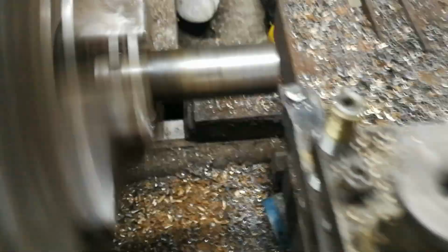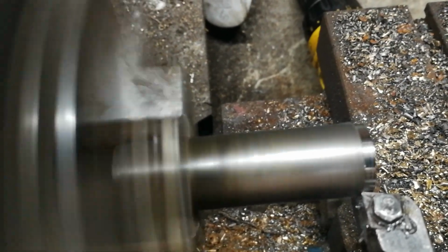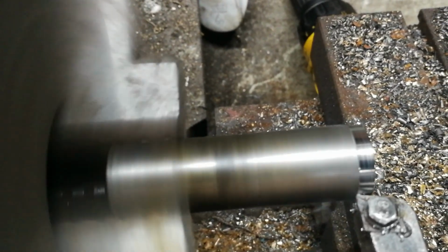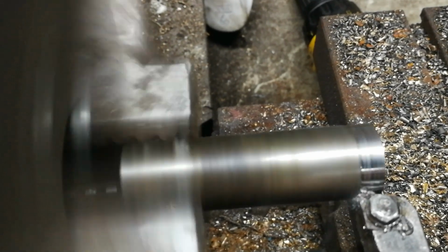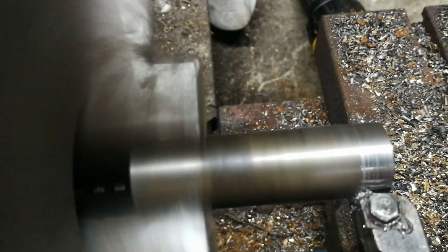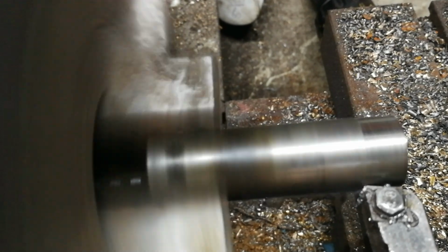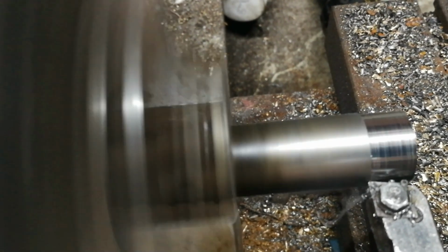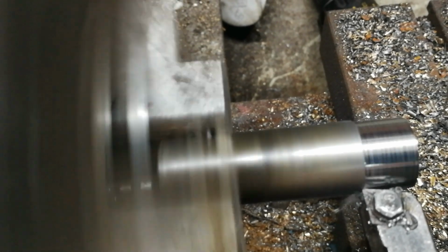You should avoid using coolant when turning cast iron or brass, as the fine filings from these materials will build up in the sump or T-slots of the machine. For machining cast iron, it is recommended a face mask should be worn due to the graphite dust that is given off. Coolant, where used appropriately, can extend the life of a tool and aid its machine finish quality.